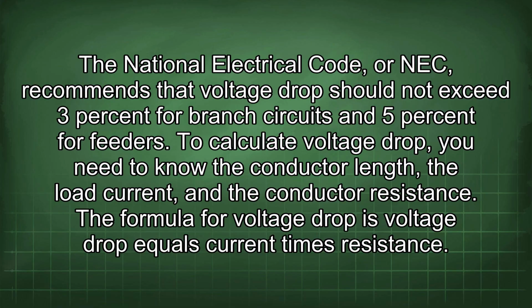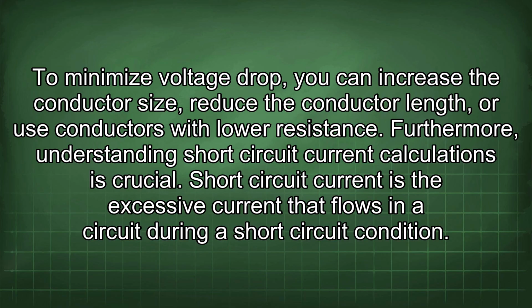The formula for voltage drop is voltage drop equals current times resistance. To minimize voltage drop, you can increase the conductor size, reduce the conductor length, or use conductors with low resistance.